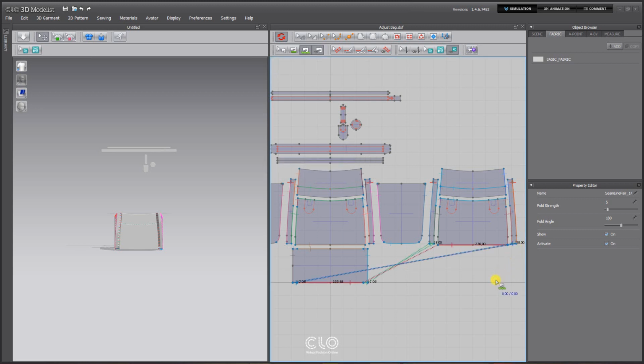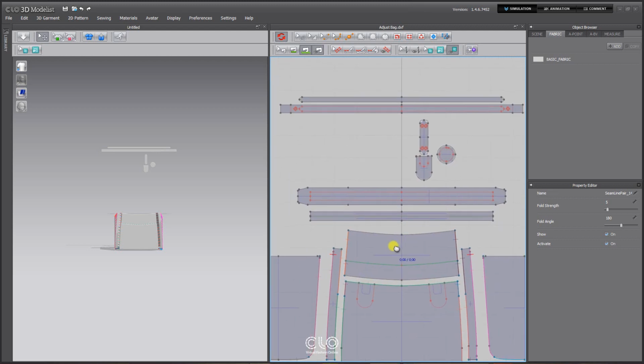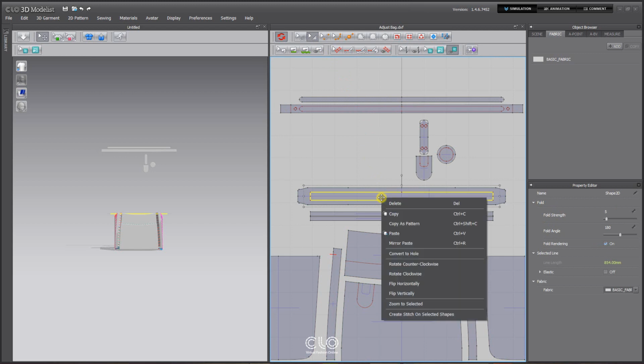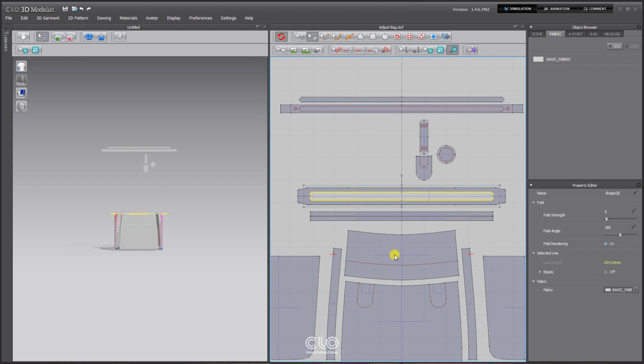Now, let's move on to the individual zipper patterns as well as the larger pattern the zippers will attach to. Before establishing the sewing lines, a hole will need to be created for the pattern that the zippers will be attached to. With the Transform Pattern tool, click on the internal shape within the larger pattern piece. Once selected, right-click on the internal shape and select Convert to Hole. Notice that a hole has appeared where the internal shape once was.